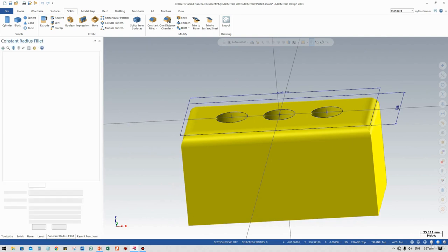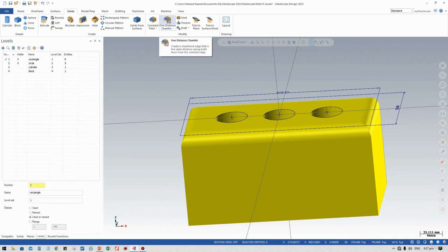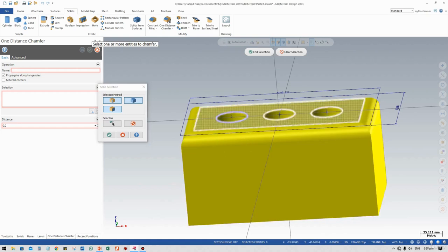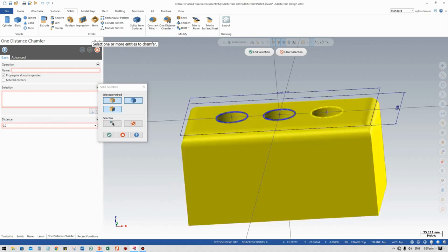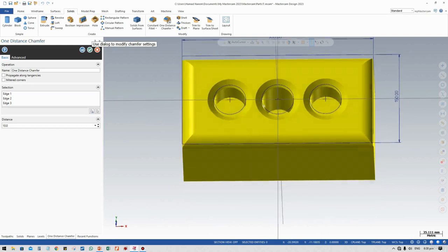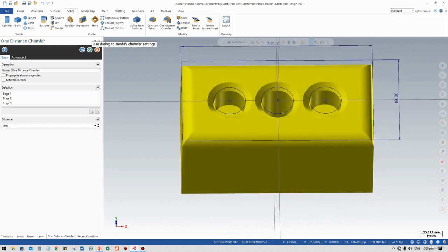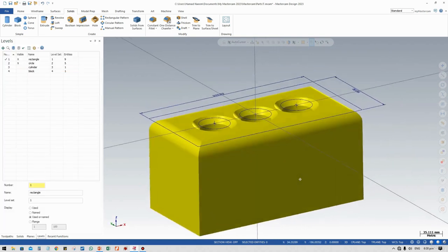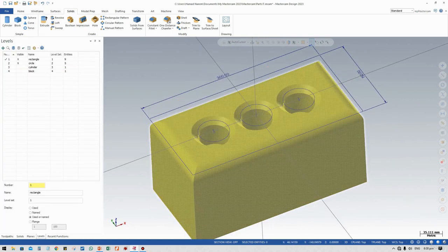Okay. So how about the chamfer? You can create chamfer around this. For example, I just want to create chamfer on this hole. Okay, and give a chamfer of, make a 10 millimeter chamfer, and just create a 10 millimeter chamfer at an angle of 45 degree here. Okay, so this is how we can create a simple geometry using the 2D wireframe,